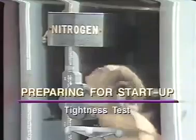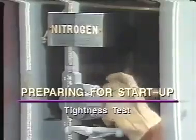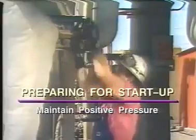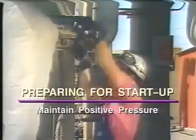A tightness test is usually performed by running pressurized steam or nitrogen into the tower. A pressure buildup indicates there are no leaks. If the pressure continually bleeds off, there is a leak somewhere in the system. After the tower is tested for leaks, the inert gas or steam pressure is released. A hydrocarbon vapor is then backed into the column to avoid pulling a vacuum.